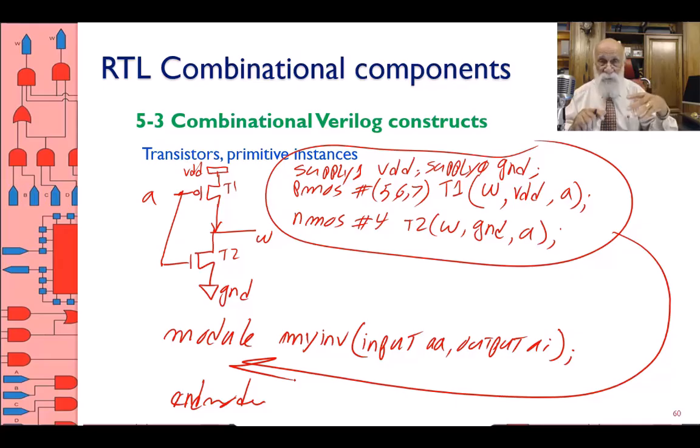Something about the use of NMOS and PMOS transistors. NMOS is always the structure. You don't mix them. Okay. You have the output. On top of the output in the direction of supply, those are only PMOS transistors. Below the output, those are NMOS transistors that connect to the ground. You cannot switch them. You cannot put NMOS on top and then PMOS at the bottom. That's because of the transistor physical property, which we are not talking about here.